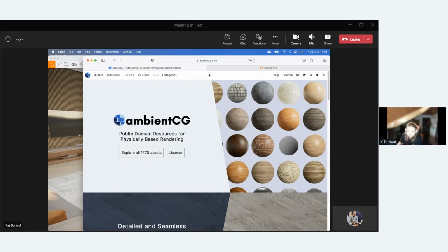Of course, you could also go in and take some photographs and just use those as textures, and that will work as well. Especially with Enscape, you've seen it earlier, it will try to derive a bump map automatically and roughness map. The only downside is they're not tileable by default. So there goes some preparation time into making them repeat with as invisible borders as possible. And that's not going to happen with your photographs by default. But there are also softwares for that.